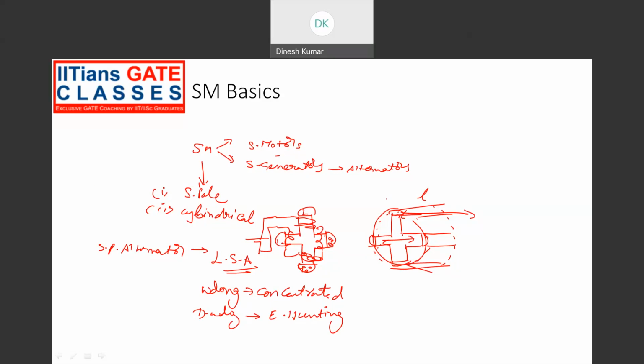So damper windings are the bars inserted in the pole shoes of the rotor. What is hunting? Hunting is nothing but the machine rotor getting oscillations. Some of the main reasons for the hunting in a synchronous salient pole machine are sudden changes in load or supply, or sudden changes in the field excitation system. That is here, this one, and loads containing harmonic parts.